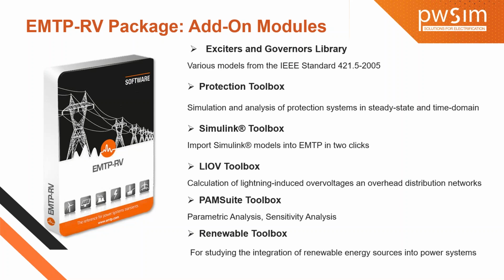Simulink toolbox. This toolbox is used to import the models from MATLAB coding and Simulink models into EMTP very easily. LIOV toolbox. This LIOV toolbox is used for the calculation of lightning induced overvoltages on the distribution networks. PAMSUT toolbox. This PAMSUT toolbox is used for parametric analysis, sensitivity analysis, optimization, and contingency analysis also.